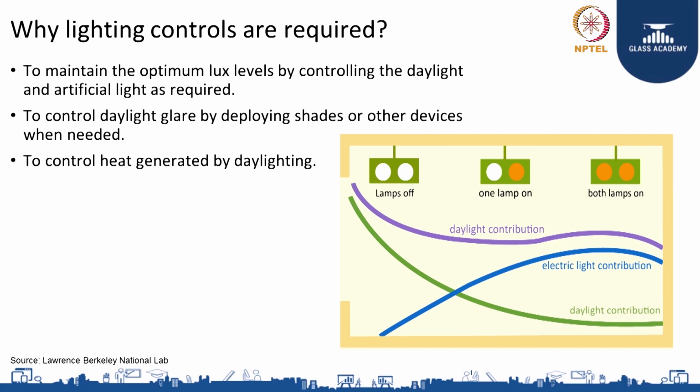Generally, we will have 3 zones in a building. The perimeter zone generally would be dimming more than the core zone, because the perimeter zone will see more daylight coming in. So in this figure you see that the perimeter zone is totally off and the middle zone, which is between the perimeter and the core zone, is 50% off, and the core zone is 100% on. So like this, we are able to compensate the variation in the daylight by putting varying artificial light and trying to achieve uniform illuminance near the targeted levels throughout the space.